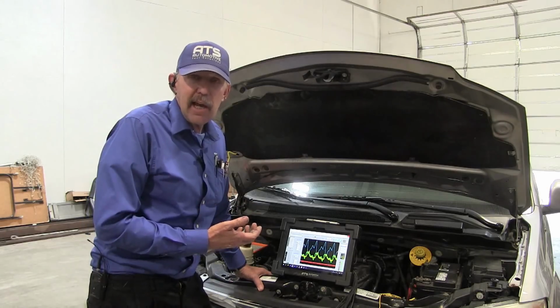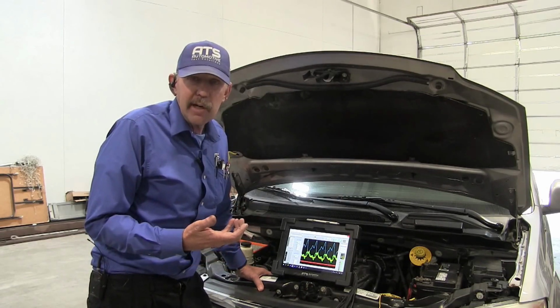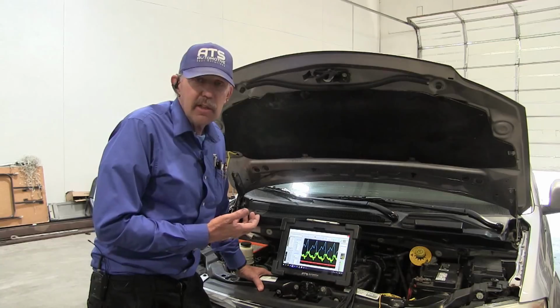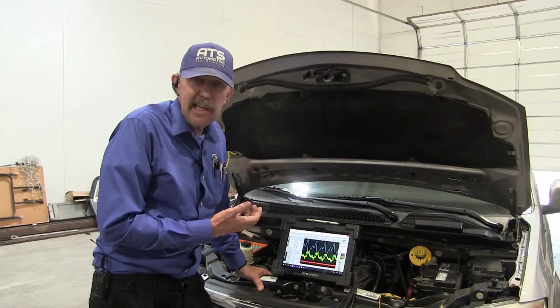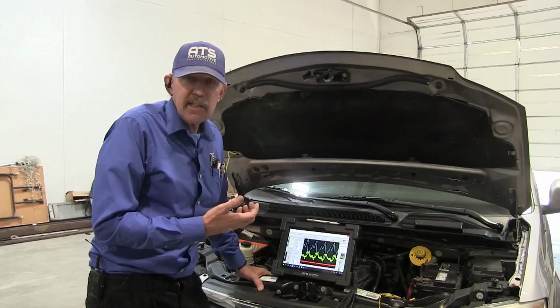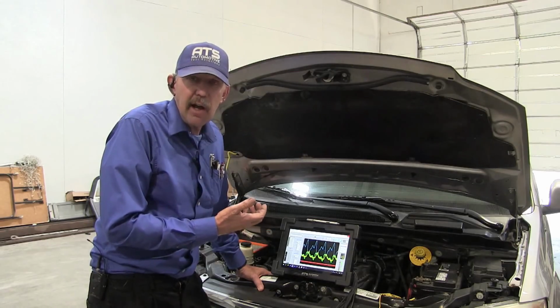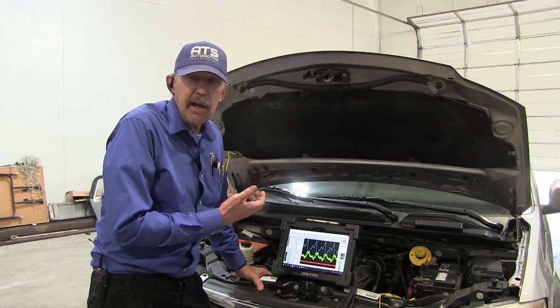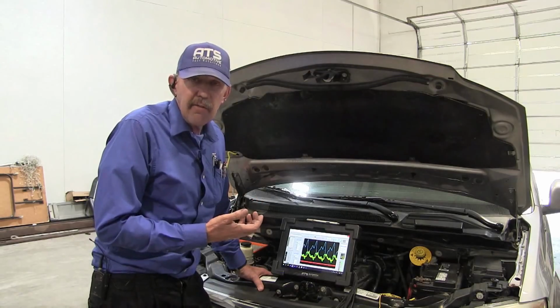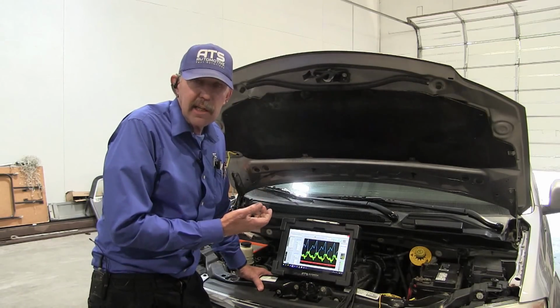We got the data. I surely didn't expect the rings to be bad, and I surely didn't expect the VCT control to be bad, to be leaking. But here we have a double problem on this car. We have the VCT solenoid leaking oil and creating a phasing issue where the cam is advanced, and then we have a problem with the rings leaking.